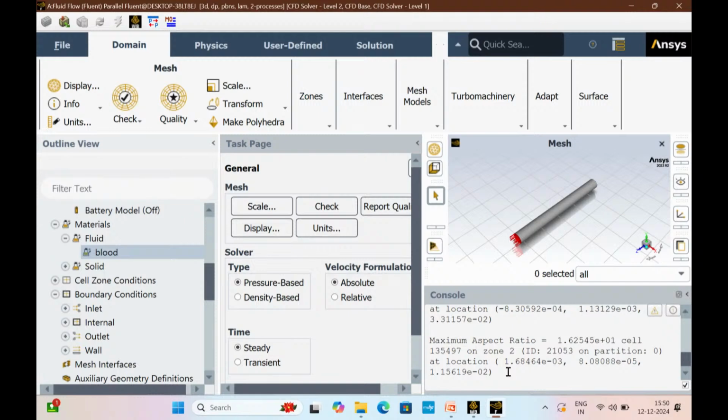Yes, for patient specific simulations you will need to give pulsatile pressure at the outlet, but here just for demonstration I am giving 0 pressure at the outlet. Particularly for the FSI simulation, the pressure value is very important. This is a rigid wall simulation. Today I think Suman sir has talked about FSI simulation, fluid structure interaction. For fluid structure interaction we need to give the exact pressure values, otherwise the deformation will not be correct.